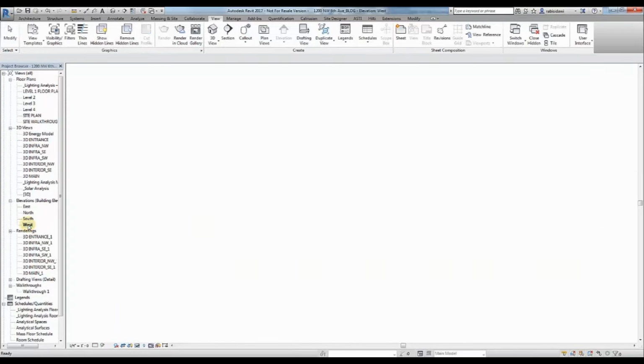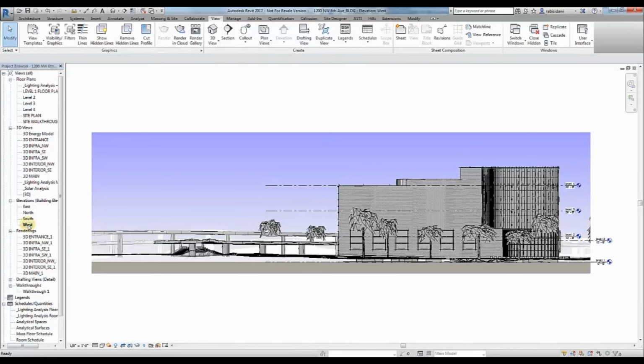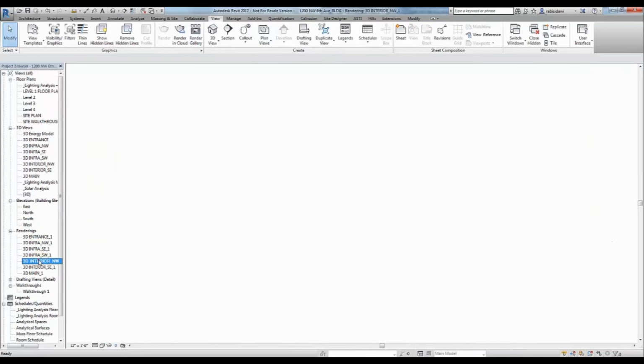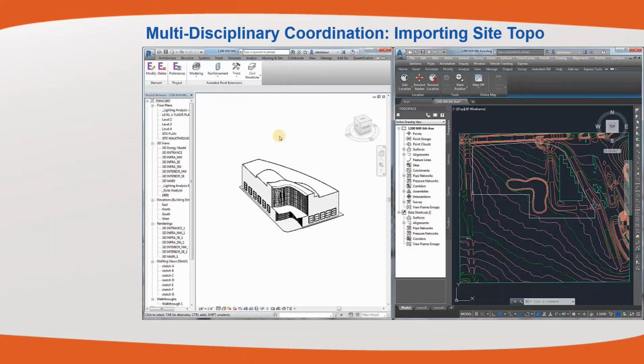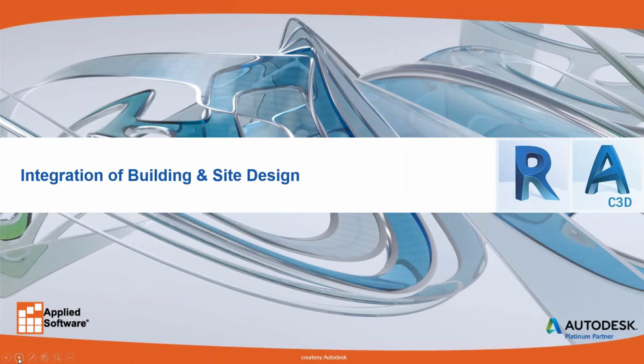Okay, so in Revit, we've just created this monochrome type presentation with elevations, and you can see the infrastructure in the background. We're using the latest feature in Revit, which is depth cueing, which allows you to fade what's in the background. And with very simple techniques of massing in Revit, you're able to apply curtain system by face, roof by face, and get some really nice results. And this is just all schematic stuff.